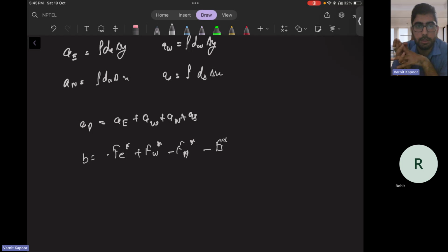So that means we have now related them to the pressure corrections. And now what do we do? Basically substitute for all these flow rates back into equation 1. That means on the left hand side, you have everything in terms of pressure correction. On the right hand side, you have it in terms of star velocities. The difference from the staggered mesh is that these dE are different and dN are also different. The dE at the face comes as the arithmetic average of dE plus dP by 2 and so on.